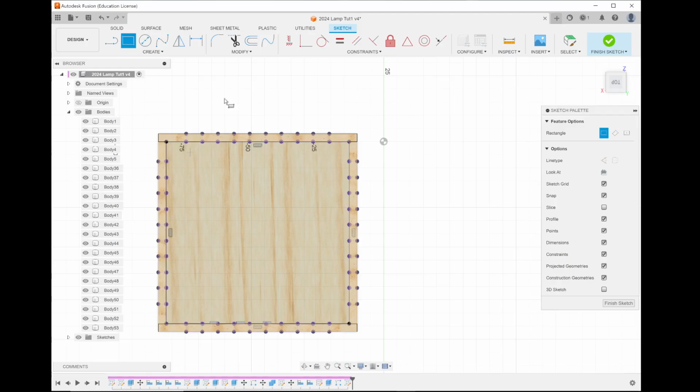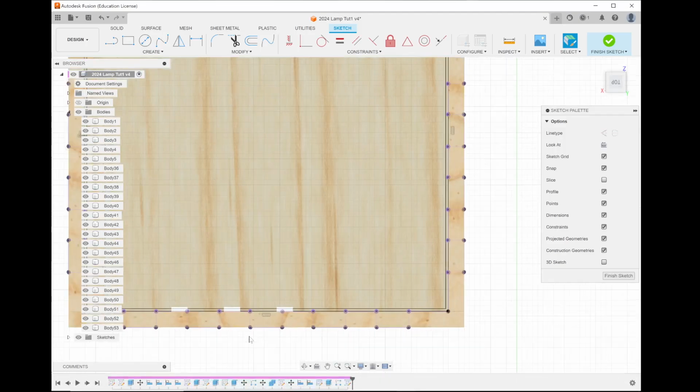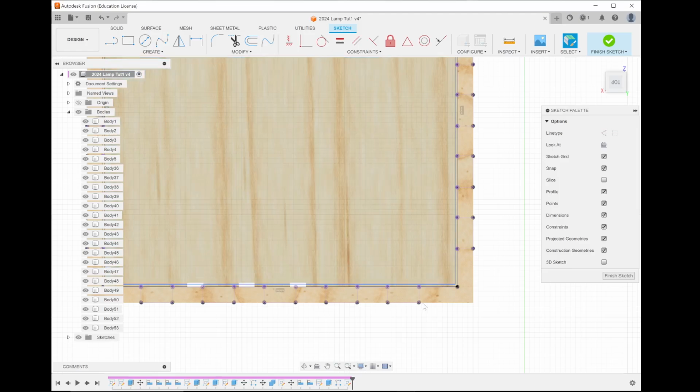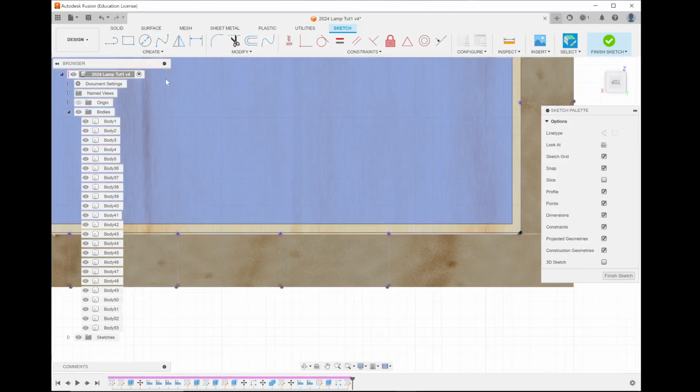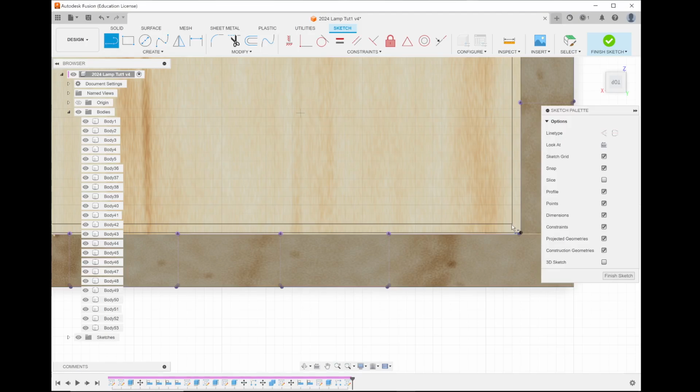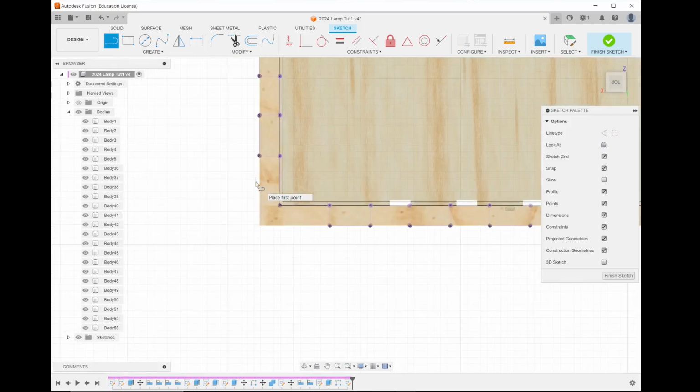we're going to offset that shape we just made, and we'll make this 0.5 millimeters thick, right? And before we finish it, these last ones are cutting over here. We don't actually want the material to be on this face, because this is where we're going to be putting our lights. So we're going to get the line, and we're going to cut into there, and we're going to get this line.